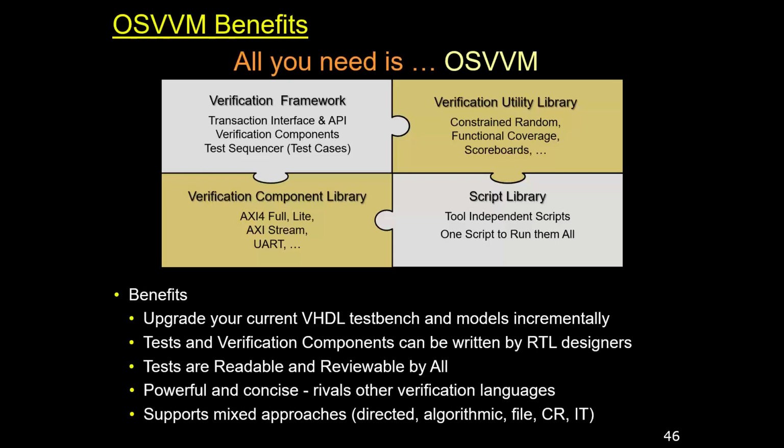In many ways, that's like throwing away all of the concurrency that's naturally in the language and switching to subprograms, but then augmenting those subprograms with the capability to fork and join. So if you love fork and join, you're going to love SystemVerilog. But if you like entities and architectures, you're going to hate it, and you're going to love OSVVM.